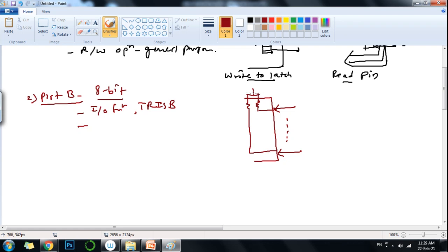We have discussed this already for the 16F628 also. Therefore, if you leave an input pin open, the status of that pin will be considered as logic 1, because of the internal pull-up. So you simply have to connect an external switch to ground to make the pin low. Otherwise, if you leave it open, it will be considered as logic 1. Those are the weak pull-ups.